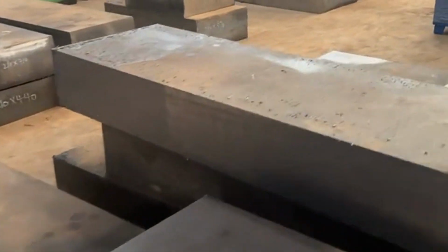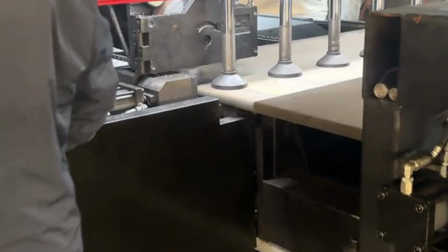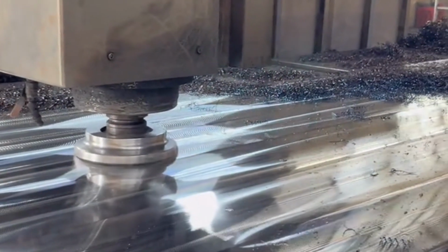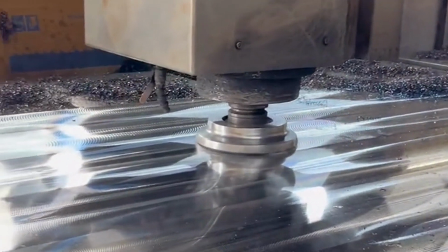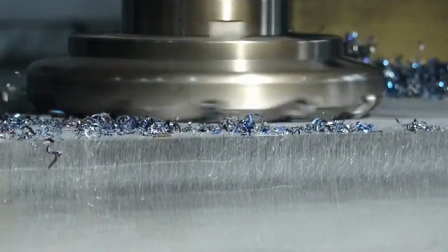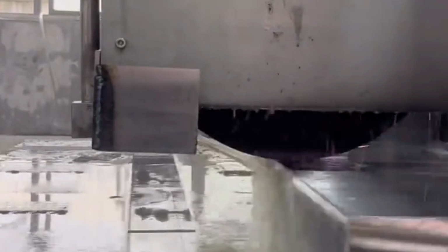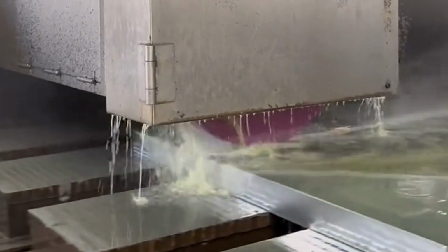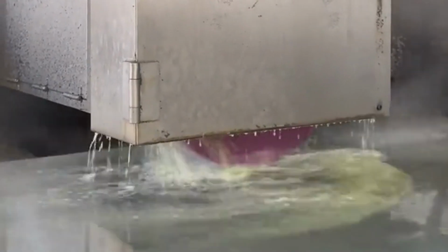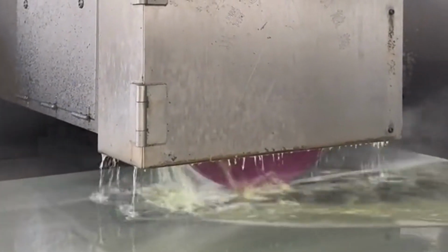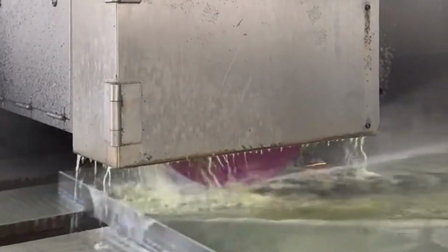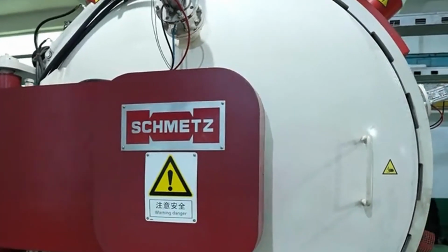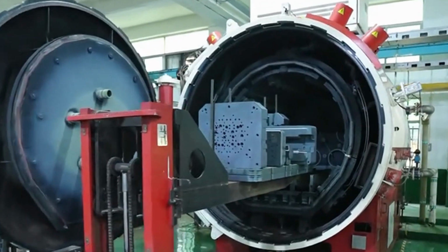After the mold material arrives, the mold engineer checks whether the material is qualified and meets the requirements for manufacturing and processing. Rough machining is then carried out, using cutting equipment to cut the raw material into approximate shapes and sizes, leaving 0.5 to 1 millimeter of machining allowance for subsequent finishing, including removing most of the allowance and machining out the basic contour. Rough machining can improve machining efficiency and reduce the workload and cost of finishing.